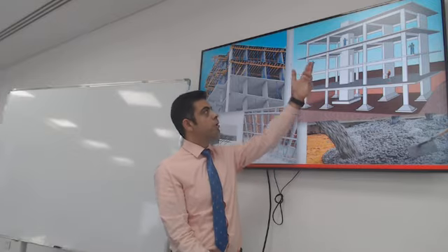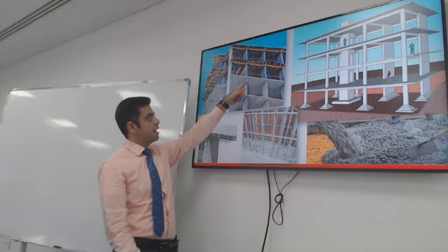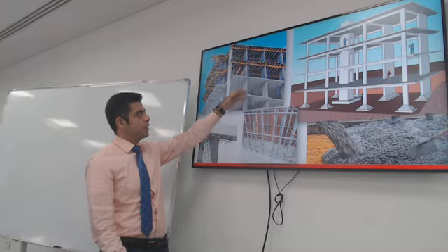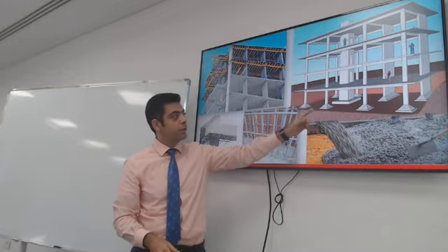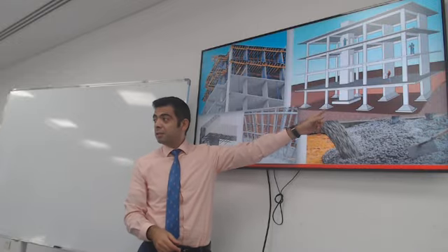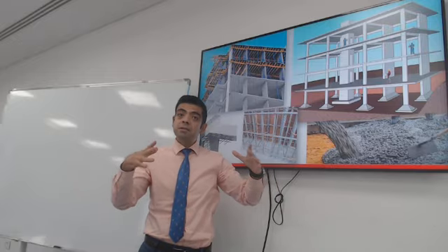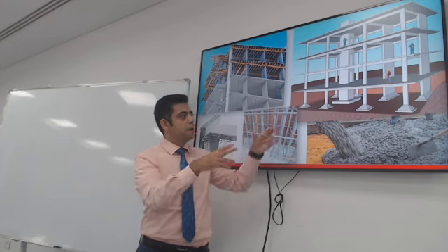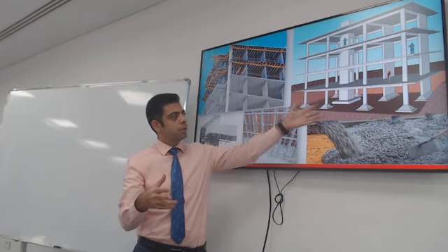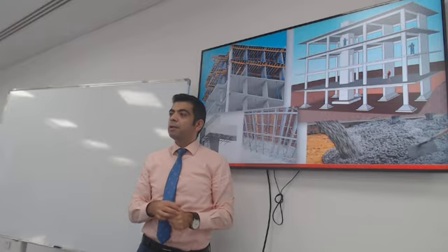That means the load needs to go through the slabs, and then through the columns. The columns will accumulate the load all the way to the foundation. You need to design the foundation and size it. The size is reasonable for the stresses of the soil. If it's too small, it will sink in the soil. If it's too big, you're wasting material, and it's probably going to result in high stresses in the foundation.